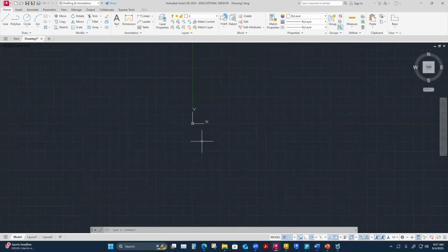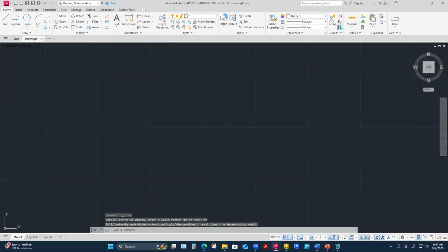And if I need to get back to something that I've lost way off screen, double click the mouse wheel. So just double click. It's like a zoom all or a zoom extents. So whatever you have drawn, if you do have stuff drawn way out in the model space universe somewhere, it's going to zoom all, meaning it's going to capture anything that you would have had way out there in a weird spot. And so if it still looks like things are way out there or weird, it means that maybe you need to delete some stuff that you didn't mean to put way out there if your zoom all doesn't work. Yeah, go ahead.